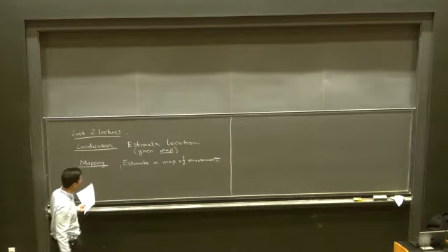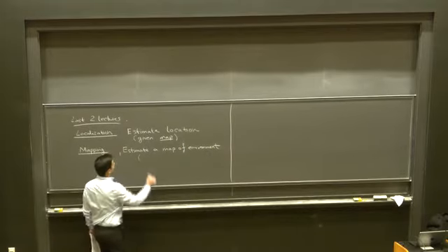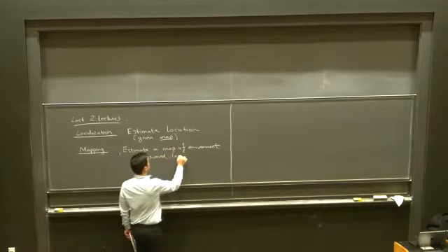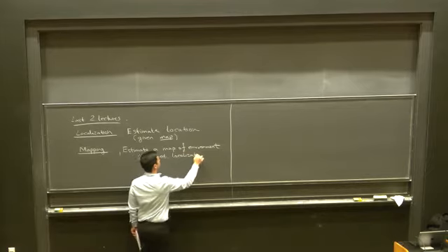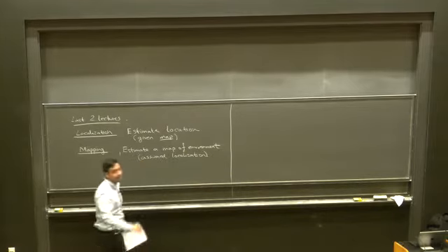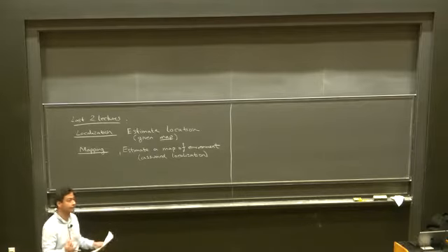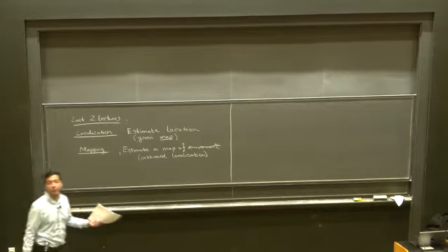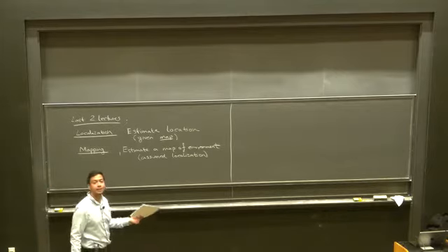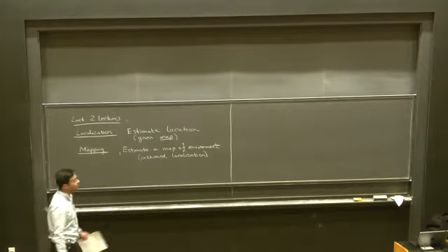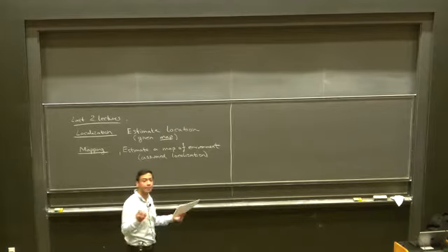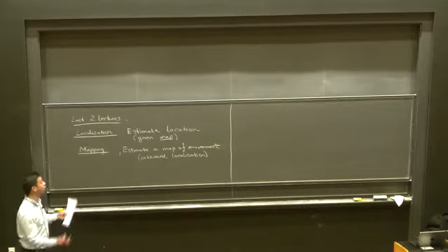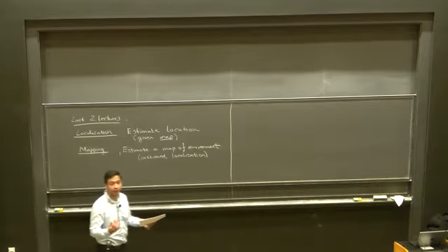And if you look back to the previous lecture, for the mapping part, we assumed that the robot had some way to localize itself in some kind of global reference frame, and all it's doing is figuring out the map of the environment. And along the way we discussed different kinds of maps: location-based maps, feature-based maps. For the most part, we've been working with occupancy grid maps. Those are conceptually relatively simple, and a lot of the algorithms we've discussed also apply to other kinds of maps.